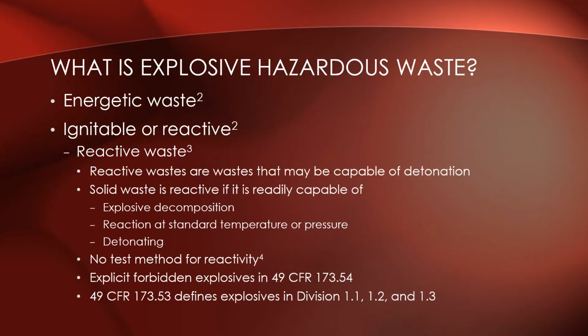So what is explosive hazardous waste? These wastes are energetic wastes, which are also known as explosive wastes. They are wastes that have the potential to detonate, as well as bulk military propellants. Energetic wastes are designated as hazardous or RCRA because they display the characteristics of either ignitability, code D001, or reactivity, code D003, or display both characteristics.